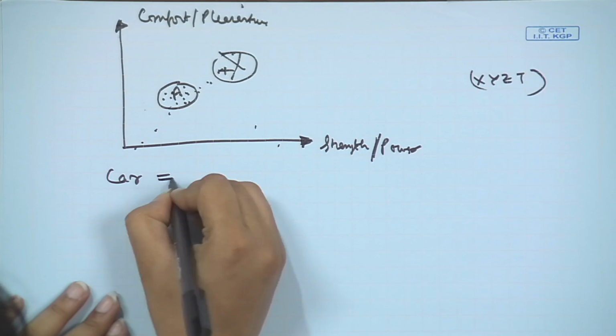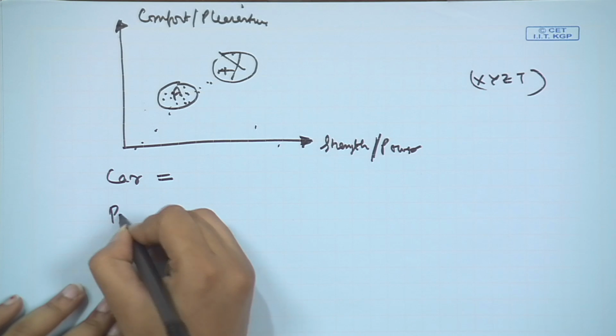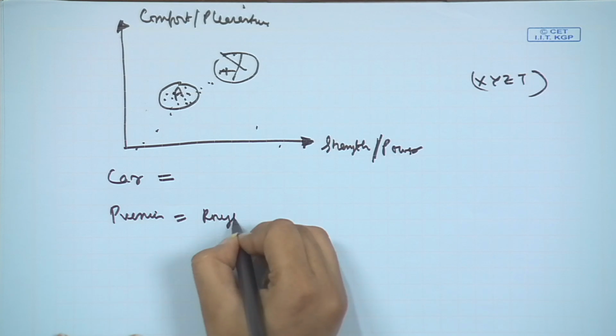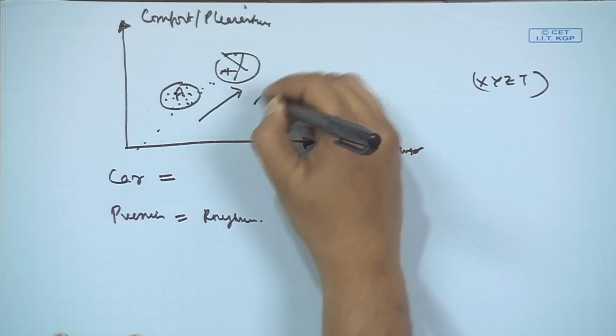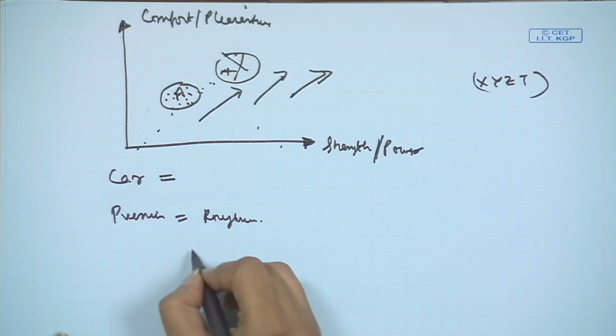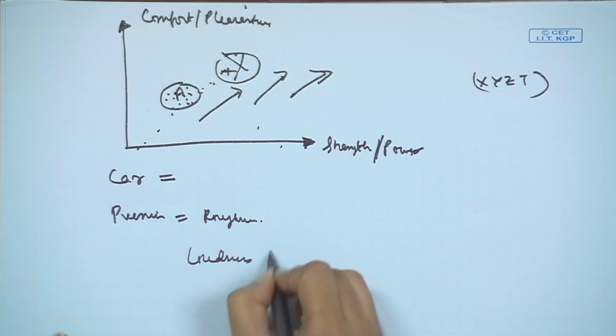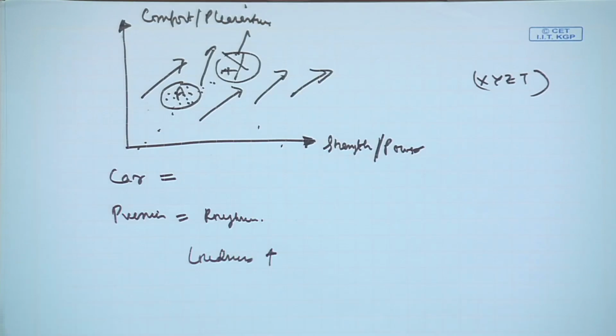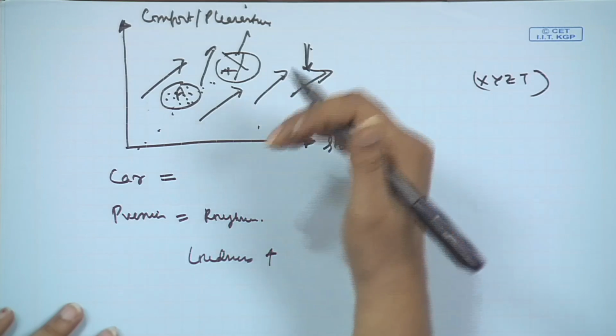Okay, so for a premium car, as I told you, what has already been found from research is that if roughness is reduced, then the subjective judgment goes up. If the loudness of a car is increased to a certain extent, then the perceived powerfulness and pleasantness go up. But after the loudness is increased further, the powerfulness will go up, but the comfort or the pleasantness will decrease. So we try to use numbers to define how humans find the sound.